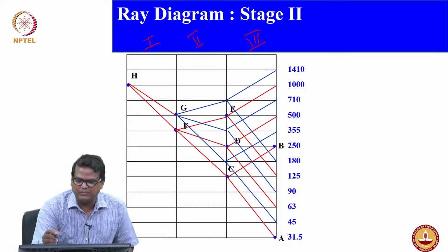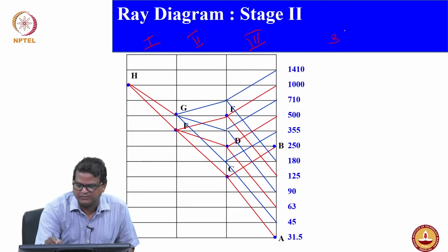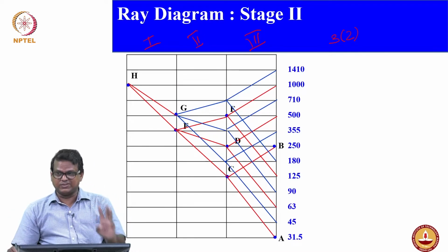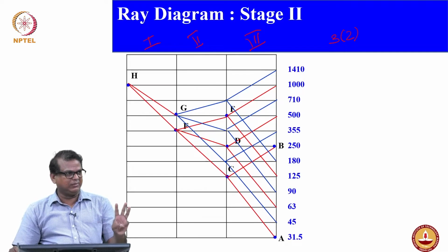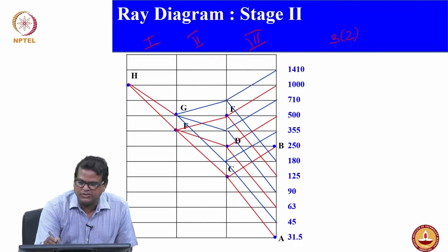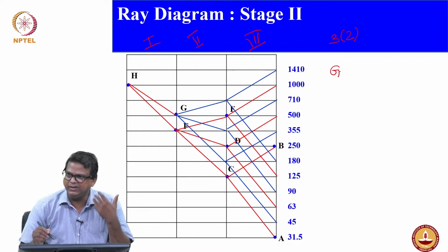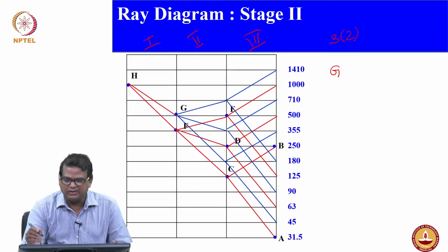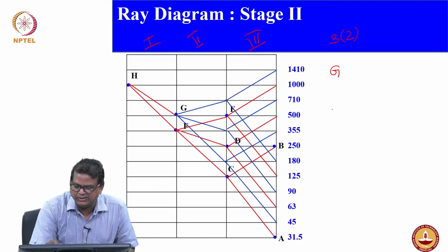What's the structural formula? 3F2, isn't it? Okay, 3F2. So you have 3F2. You needed 3 gears. That means one input will give three different speeds. Okay, let's check for G. I have taken the G. That will be the input to my second stage. We get a 2 speed G, and G and F are both 2 input speeds.